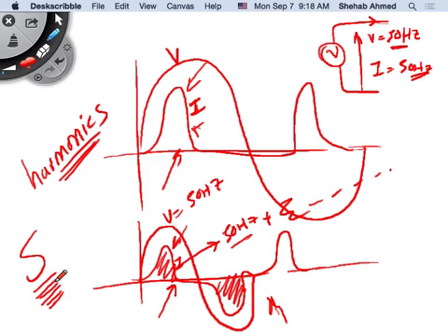Remember, the apparent power rating of a transformer is the voltage's RMS value multiplied by the current's RMS value. So I'm going to calculate the RMS value of this waveform, not only the fundamental. A lot of extra harmonics flowing in there contribute to increasing the apparent power rating of my system components.